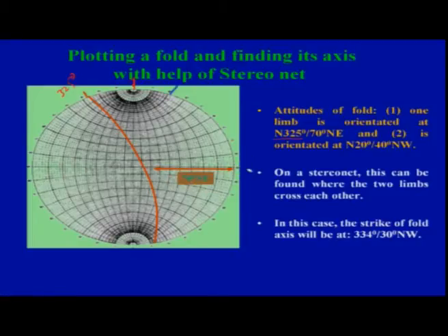Then another one you are marking is north 20 degrees. So you have 10 and 20 here. Again the amount of dip is 40 degrees, which is northwest, so you have to go in this quadrant. This is your west, and again you have taken 10, 20, 30 and 40 here. You will move this towards north and then bring it parallel to this one here, and that will give you the plane. So you are getting this plane.